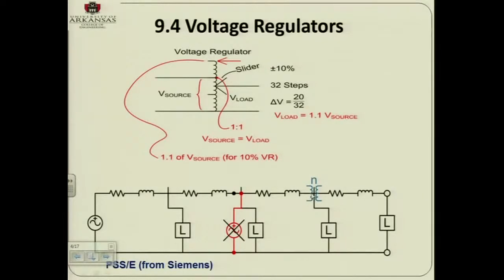Then you have to go and put shunt capacitors here. So what you do is, after you do the first pass, you look for the voltage at the last node, and if it's below 95%, you do not have voltage regulation. Then what you do is you look at the largest node, and then you are going to put shunt capacitors. And if you look at some of the slides that you have here, they show you how to calculate the shunt capacitors.